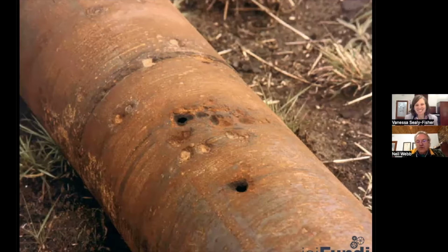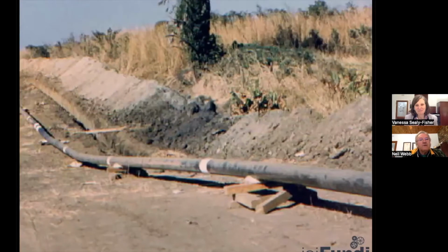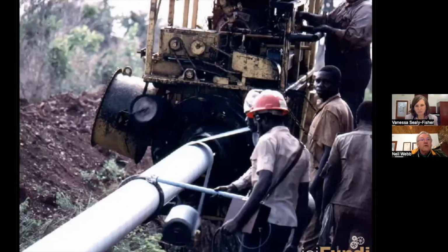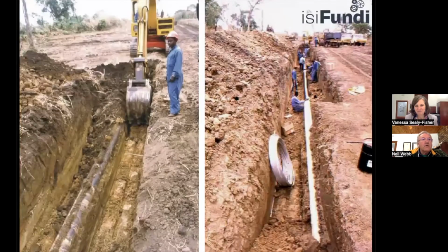And those sections were then replaced with a new factory coated pipe. Then there were sections of the line where the pipe itself was in good condition, even though the wrapping had failed. And these sections were line wrapped. There you can see an overline wrapping machine with the holiday detection rolling spring running along behind it. There were sections where there were isolated areas of wrapping damage with not much in the way of corrosion.